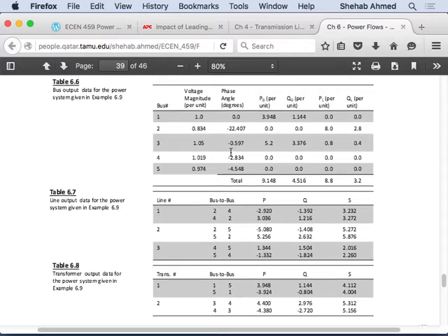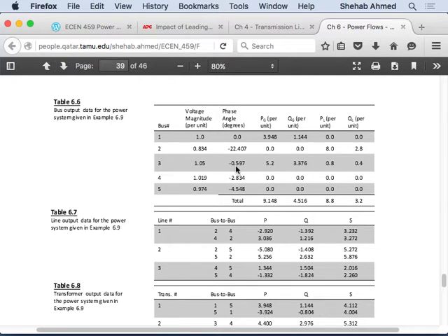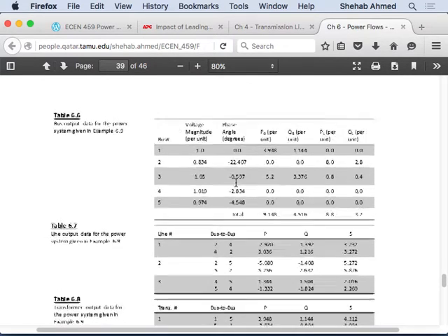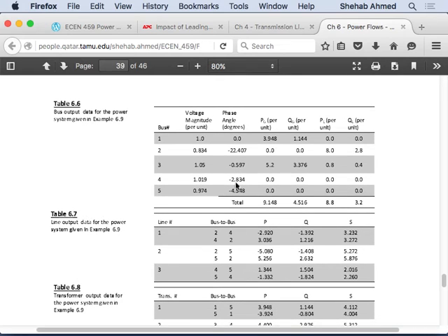So the other thing is, look at the voltages. All the other angles are close to zero. Fine, for bus 5 and bus 4, they're higher. So this 22 corresponds to both the real power and the reactive power. It's the power angle of the generator, okay, and the angle affects both real and reactive power, but I was going to explain something now that will answer your question. Then we're going to do the phasor diagrams later.